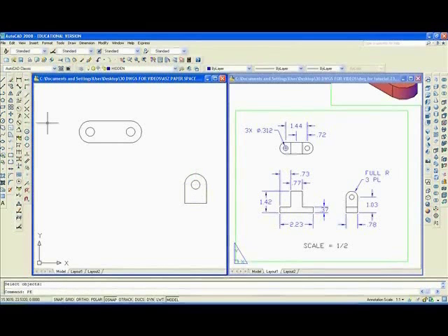Now I want to go to Polyline Edit, PE Enter. Make that a polyline, yes. J, Enter. I want to join all the lines in the perimeter, Enter. And do the same thing for the other side. Yes, J, Enter.